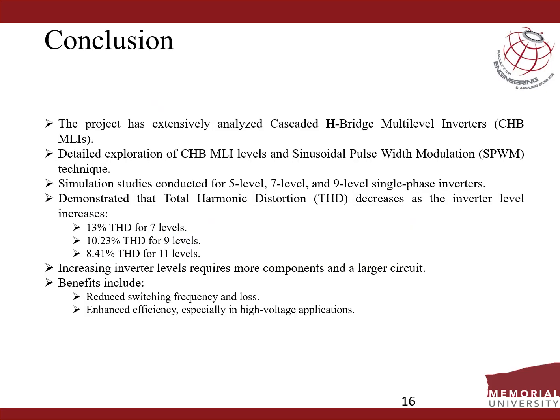Here comes the conclusion. The project has extensively analyzed cascaded H-bridge multilevel inverters and a detailed exploration of CHB MLI, which is known as cascaded H-bridge multilevel inverter levels, and the sinusoidal pulse width modulation technique. Simulation studies were conducted for 5-level, 7-level, 9-level single-phase inverters, and it is also demonstrated that the THD decreases as the inverter level increases. As I have discussed earlier,